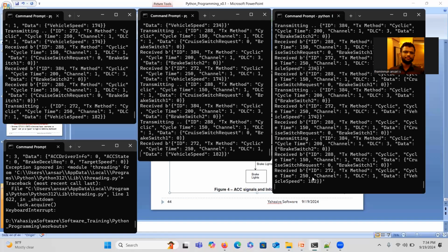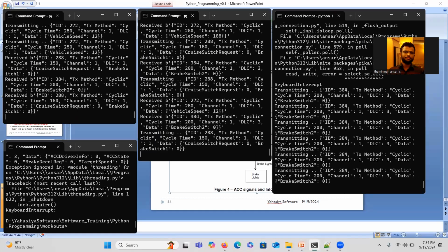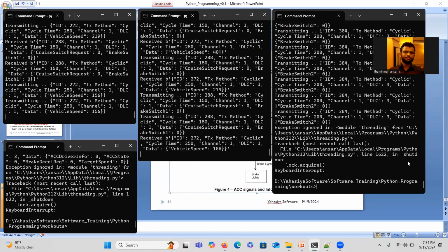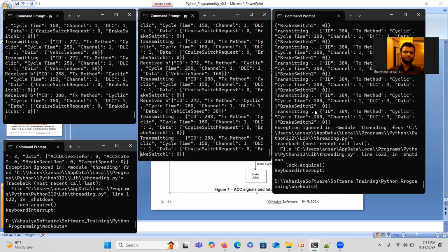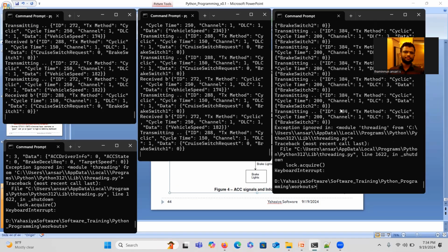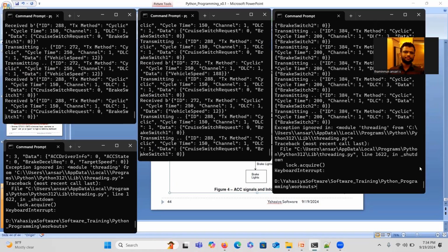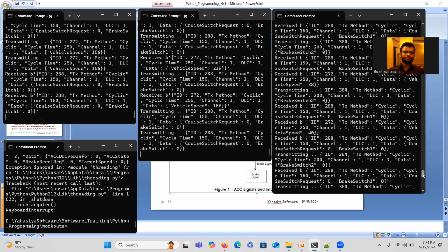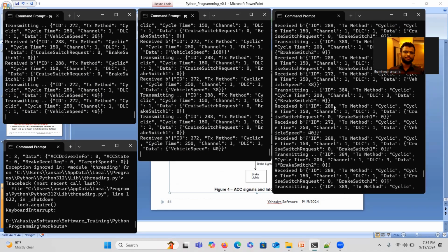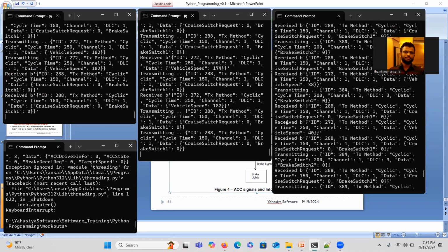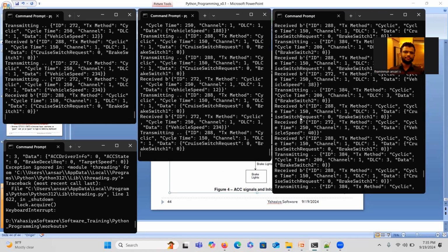Let me check that. Transmitting 384. When it is receiving, received ID 288, brake switch request, maybe from ICM.